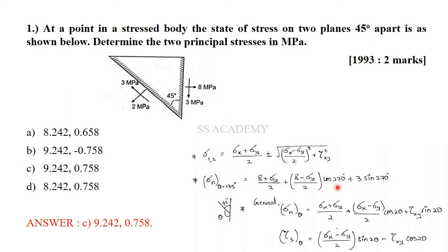Similarly, this is not the only formula to find sigma y. We can also find it through the shear stress formula in an oblique plane. This is actually normal stress in an oblique plane whose angle is theta, which can be 135 degree or 25 degree, any degree. Similarly, for tau theta, for any theta, it is ((sigma x minus sigma y)/2) sin 2 theta minus tau xy cos 2 theta. The same sign conventions are used. Similarly, the theta is calculated as shown here. So, using this also, we can find sigma y.